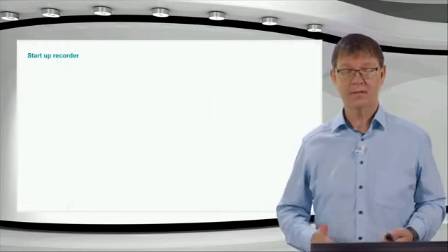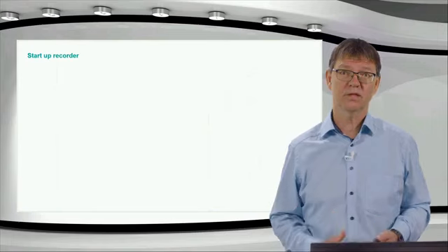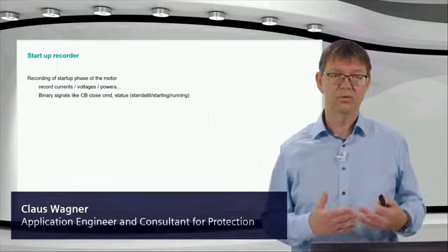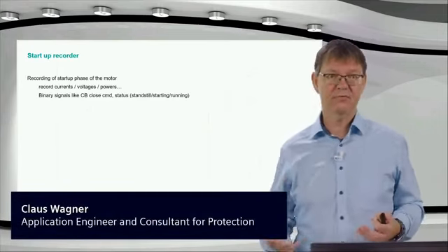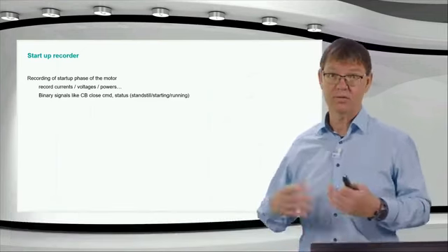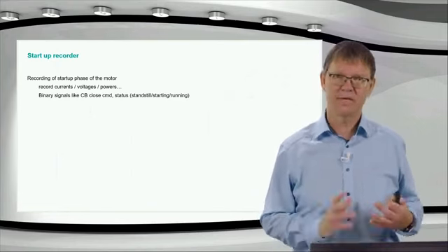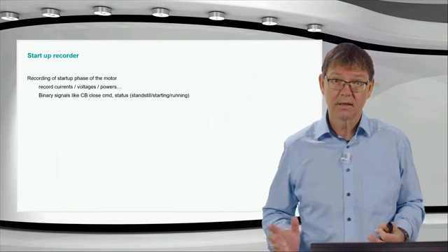Let's start with a startup recorder. So it's a built-in function now in the motor protection. And what do we do? We record the startup phase of the motors. What can we record? Currents, voltages, power, binary signals like the circuit breaker close command, status of the motor, and so on.